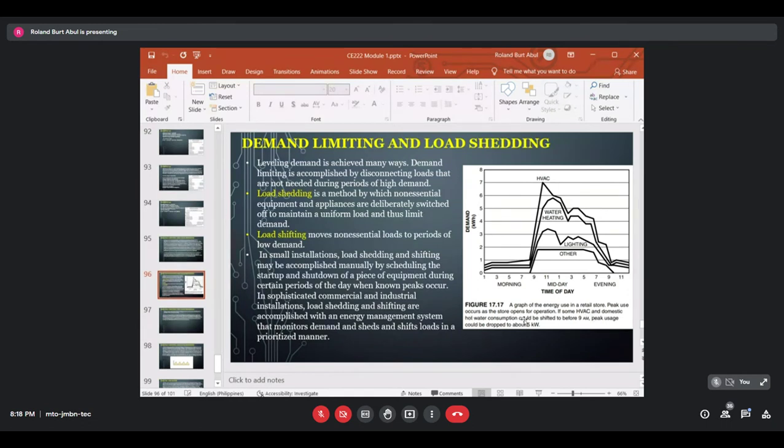So this additional charge appears excessive but is rationalized because utility companies are legally charged with the task of providing power regardless of demand. So a utility company must have the extra generating capacity to produce electricity during periods of peak demand, like during the afternoon of the hottest day of the year, even if this extra capacity is used only a few hours per year. Simply, the demand charge is needed for the utility to recover its investment in extra generating, transmission, and distribution capacity that is required to meet infrequent peak electrical demands.